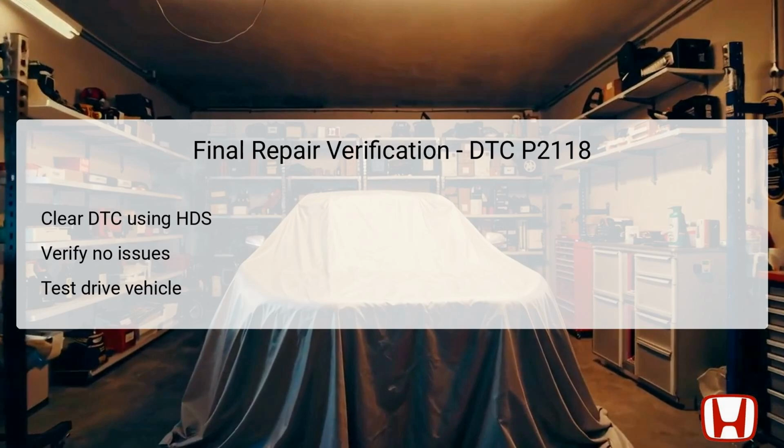A test drive is also a vital component of the verification phase, allowing the technician to experience vehicle performance firsthand. During this drive, any hesitation, abnormal behavior, or warning lights should be monitored closely. If no further concerns arise, it confirms the previous repairs were effective, enhancing the vehicle's reliability and ensuring it operates safely and efficiently on the road.